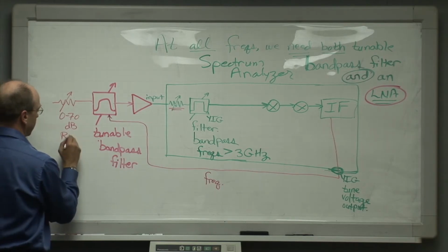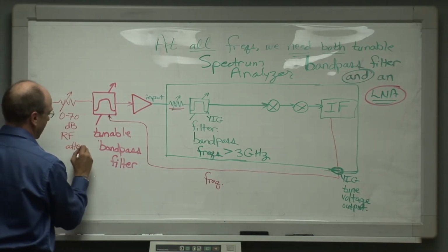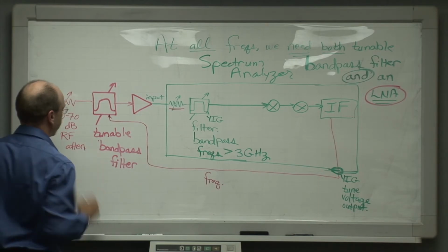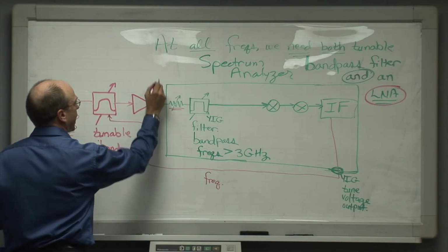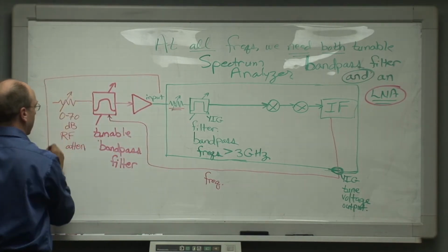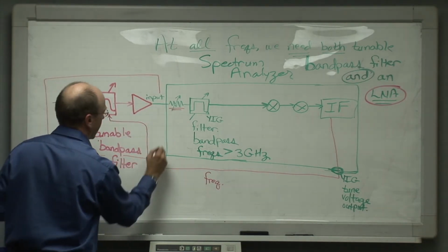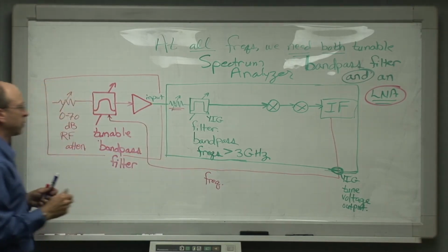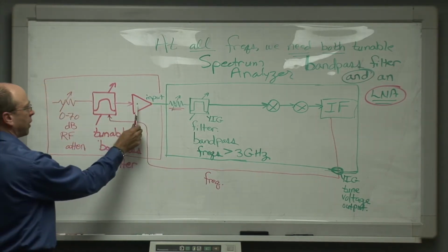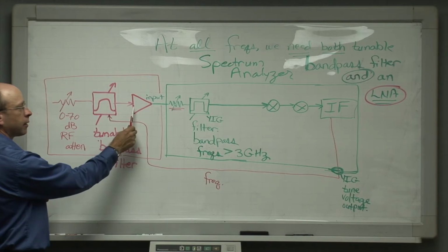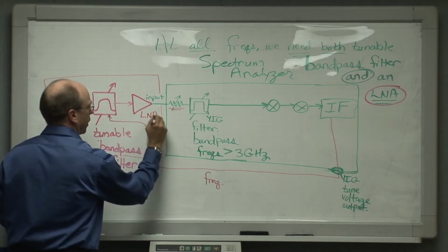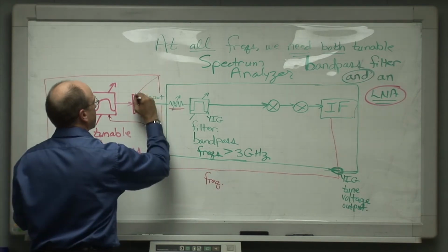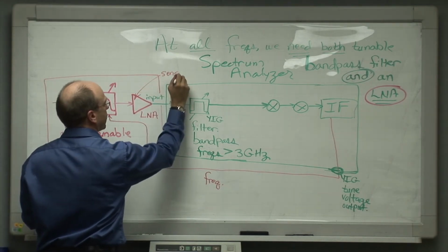of RF attenuation. Now, here's the funny if not ironic part. What we've done here, as I've diagrammed it, is to draw a front end which we have to provide, which actually has components which in one sense or another are often redundant to what's inside the analyzer. That includes the low noise amplifier, and this is where we get our sensitivity, the necessary sensitivity.